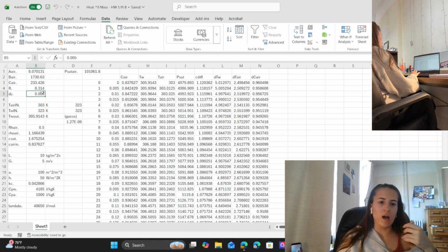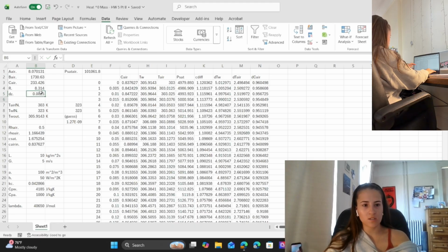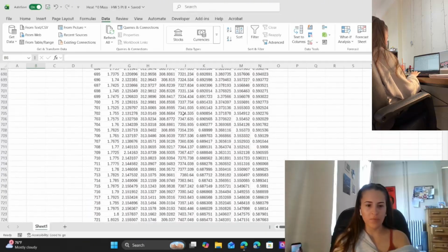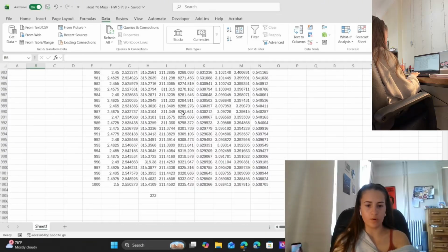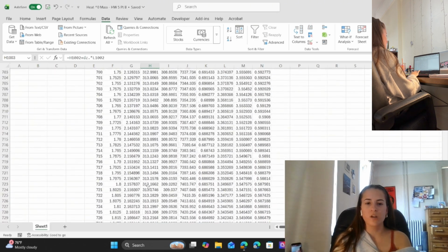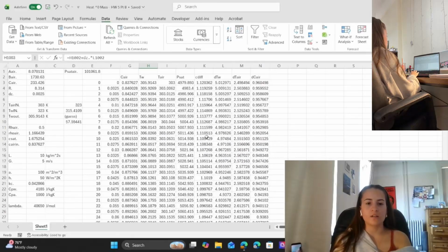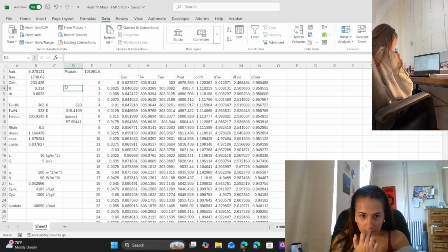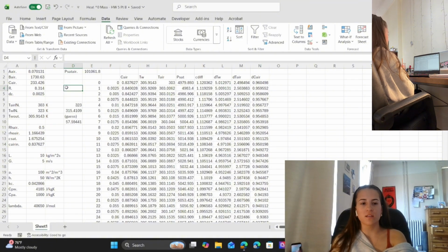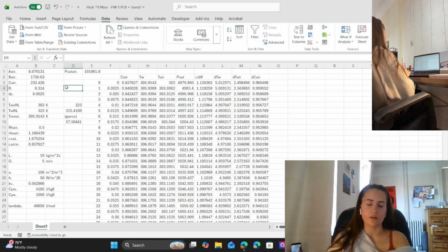So that just goes to show that more humidity in the air when it's coming in makes the cooling tower less efficient. And then another thing that you can change is also the height of our tower here. So this is going to change our values once again, because now we only have a tower with a height of 2.5 rather than 5, so that cut it in half, and so now that's changed this value drastically too, once again. And that makes the tower less efficient too, because the temperature of the water coming in, well, actually, that makes it more efficient because the temperature of the water coming in can be hotter. No, it's still colder. Sorry, I'm getting messed up.